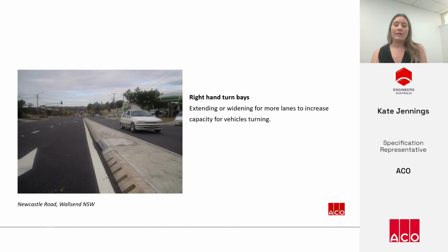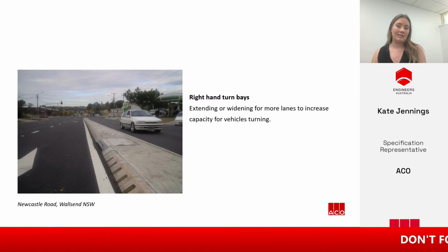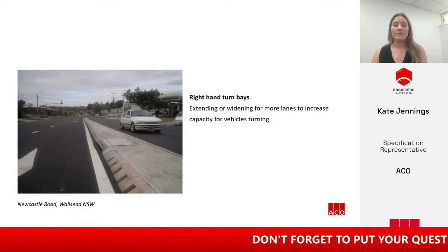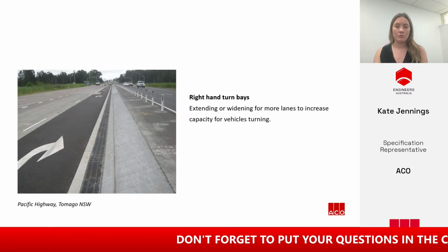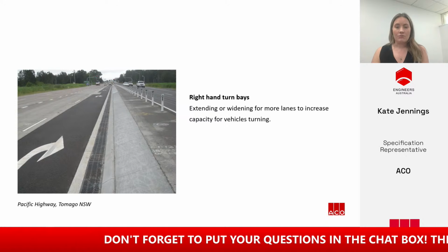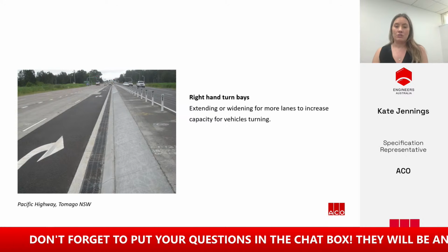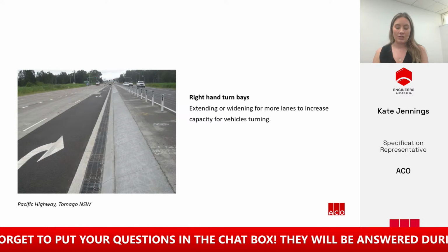For right-hand turn bays where you're trying to fit more lanes into an existing area, slotted curb drains can be a really helpful solution to give as much space to the roadway as possible. But some engineers or road authorities may prefer graded trench drains to slotted drains in this application.